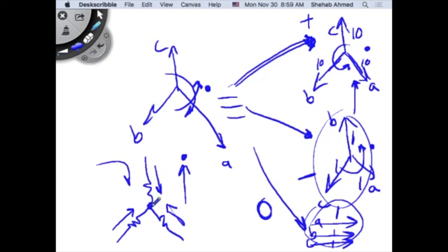So what will be the sum? 0? It will not be 0. It will be something, because these are all three in phase. They will cause current, so it will not be a balanced system either, right? This is like plugging the motor, applying a field in the motor that is stationary. Only balanced phasors applied to a three-phase load will generate a three-phase rotating MMF.